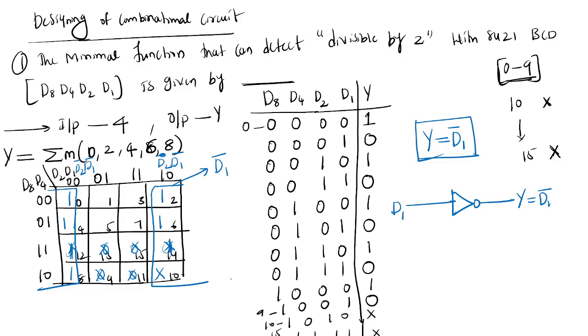No, sir, octet. We have that one in the 10th block, sorry, 6th block. That's why we are pairing that also. In 0, 4 and 8 blocks one is there. 2, 6, 10 blocks, 10 also we need to consider as one. If we didn't do that, it would be alone with one and can't be paired with any other block.